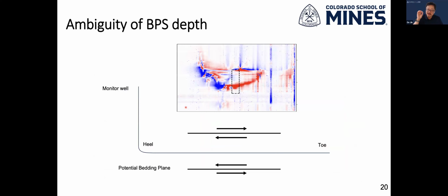So unfortunately, within the fiber itself, using only the strain measurement, we cannot tell, because the strain measurement of the fiber is a single-component measurement. So we can only measure strain. Everybody knows that strain is a tensor, right? So I have its rotation. All we can measure is this strain tensor projected along my fiber well direction. All I can measure is whether the fiber is being extended or compressed along its axis.